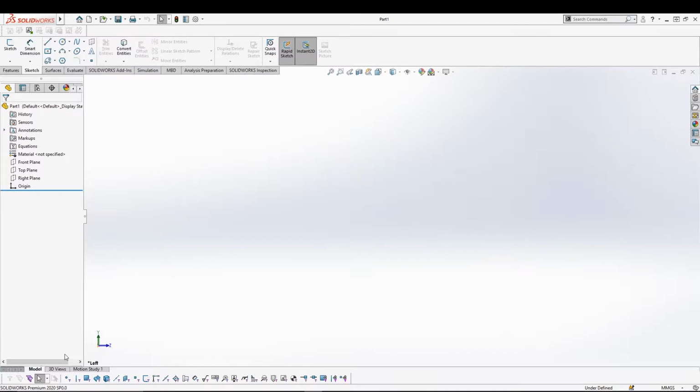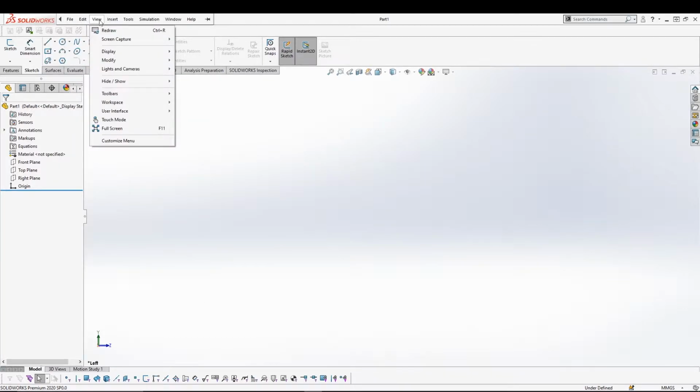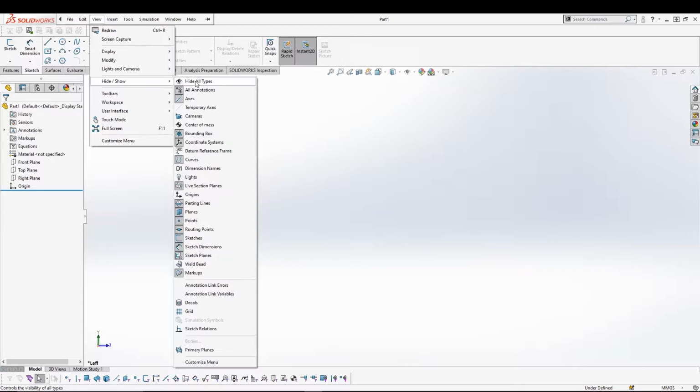Right? All right. So right now, if you see our window, we don't see any origin in my working space. So let's say I want to see my origin. All I can do is go to view and go to hide and show, and from here I can show my origin.